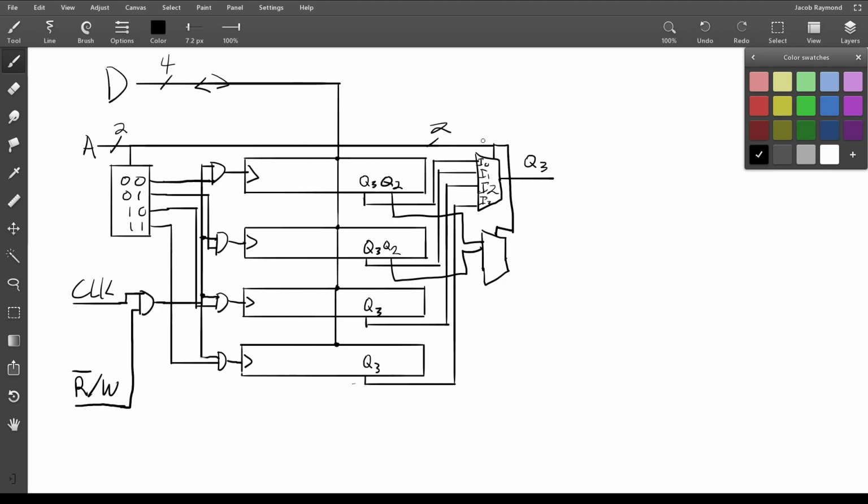And keep in mind, this is 2 variables, so all of the selector lines will just be whatever the address bus is, because we're using the address to choose which of the bits that we want from which number that is stored. Keep in mind that you're not taking all of the bits from a single register and passing them all as the different inputs of the multiplexer, because if you do so, you're only going to be choosing one of the bits of your number.